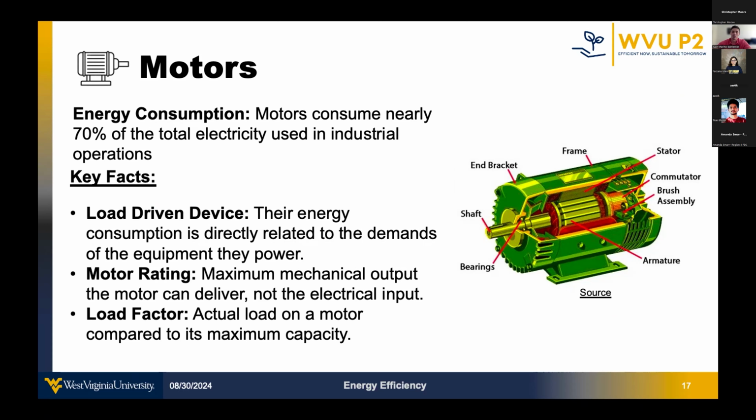Then the load factor is a crucial measure that compares the actual load on a motor to its maximum capacity. Motors operating at or near their optimal load factor are more efficient. Running a motor significantly below its rated load can lead to inefficiencies and wasted energy.